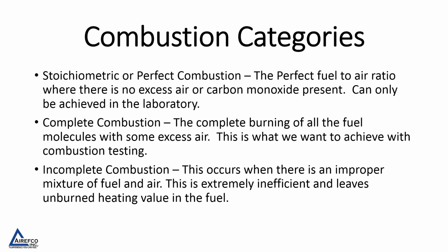There are different combustion categories. Stoichiometric or perfect combustion is the perfect fuel to air ratio where there is no excess air or carbon monoxide present. This can only be achieved in the laboratory. There is complete combustion, where there is complete burning of all the fuel molecules with some excess air. This is what we want to achieve with combustion testing. And then there is incomplete combustion. This occurs when there is an improper mixture of fuel and air. This is extremely inefficient and leaves unburned heating value in the fuel.